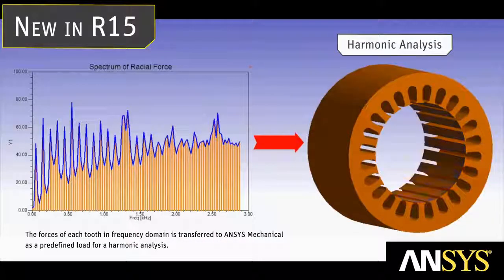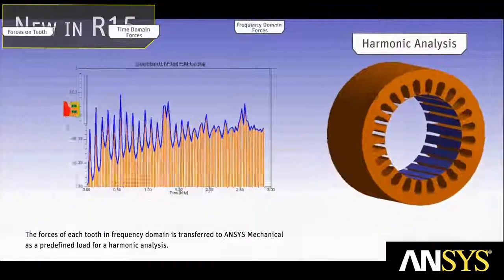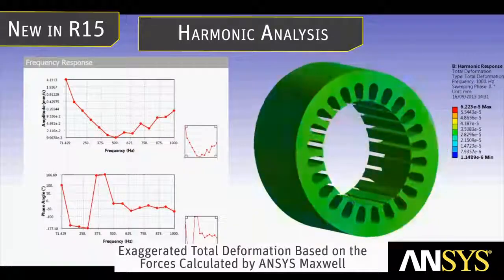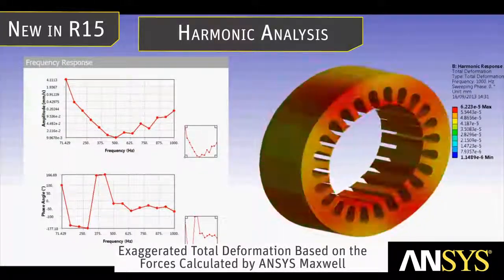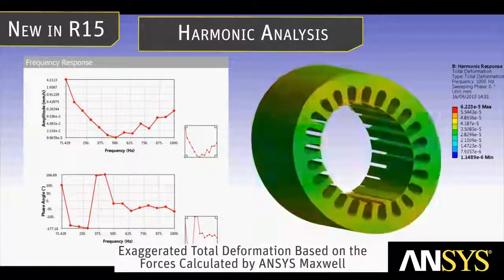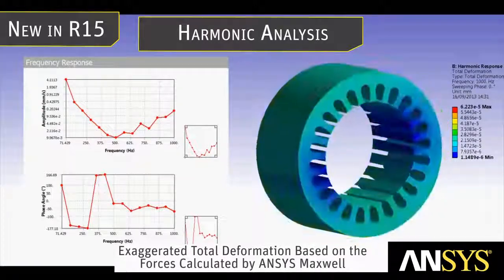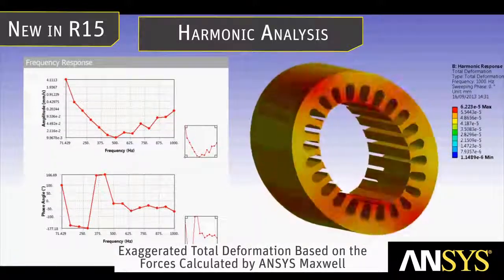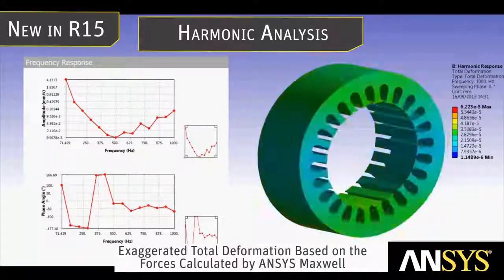We convert transient time domain stresses into a frequency domain spectrum, which in turn is transferred to ANSYS Mechanical for harmonic analysis. These steps are completely automated. Here you see the stator deformation based upon the forces calculated by Maxwell with Mechanical. The deformation is amplified to help visualize the effect. It is this deformation that becomes the source of the acoustic noise.